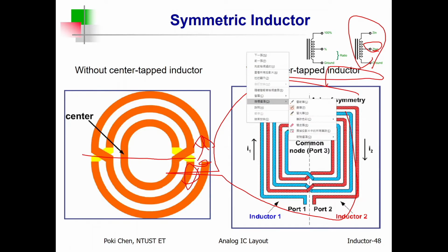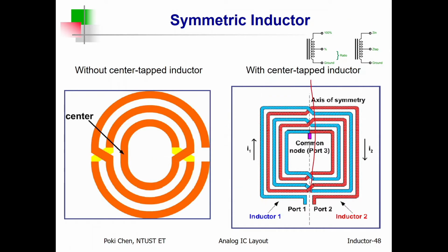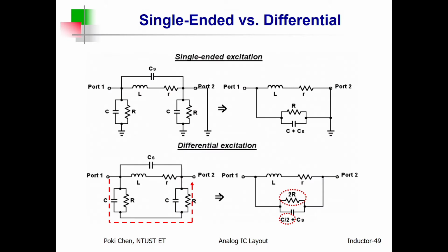Anyway, anyhow, again, you can see in the middle, to the left and to the right, they are symmetrical. They are symmetrical for your first terminal and the second terminal, right? And where to put the middle terminal, the tapping point? If it is 50% here and 50% there, then it is in the middle. In this way, the layout can provide you the best performance.